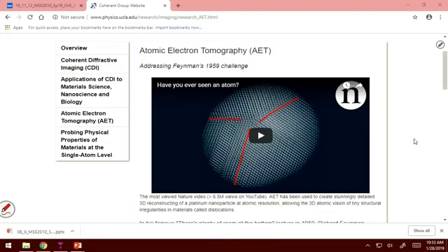And so this particular particle, because it's platinum, it's used for heterogeneous catalysis. So this is huge in chemical engineering, systems engineering, for automotive applications and a number of purification applications as well. But the atoms right at the twin, because there are voids that you see in the figure in your book, those atoms are less stable relative to the atoms that are in the bulk, so to speak. So these atoms at the surfaces are more reactive.